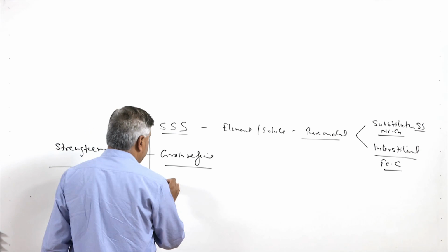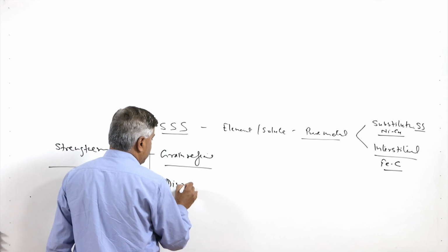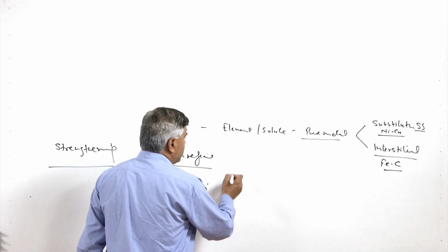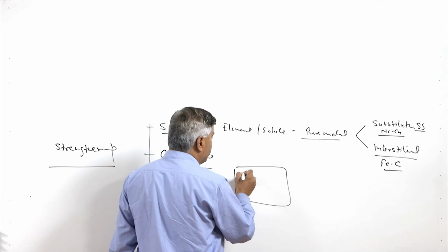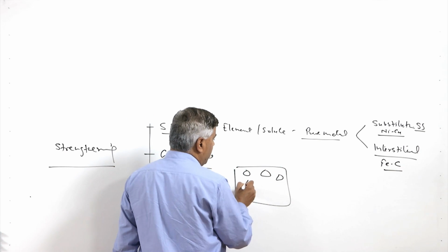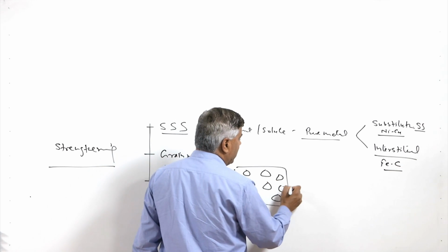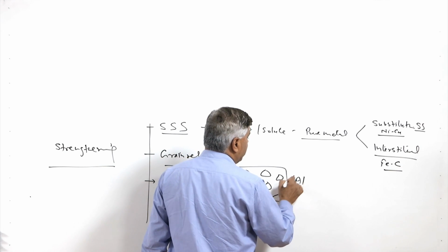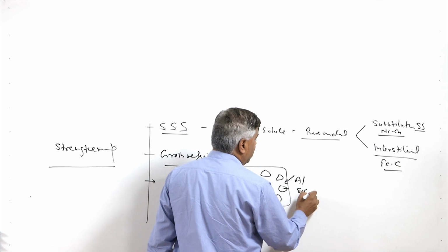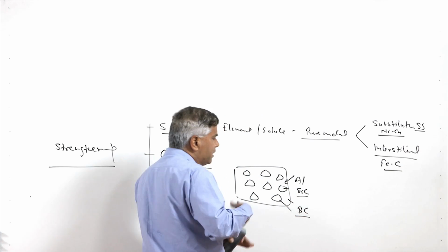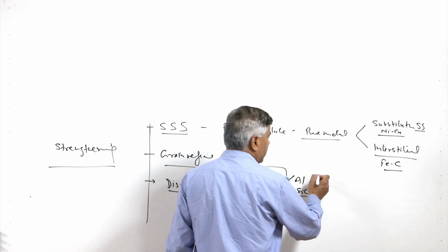Another is dispersion hardening. Dispersion hardening is used when the soft metal matrix is reinforced with hard constituents which provide support to the soft metal matrix. So, an aluminum matrix is fitted with high hardness silicon carbide or boron carbide. Such kinds of hard particles are reinforced.